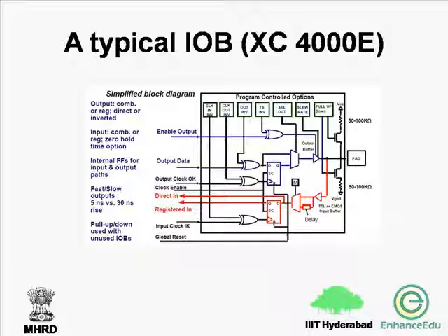So from a technology point of view, in an FPGA chip, the same pin can be used as an input or an output port, but because of the connectivity restrictions in the board, in which a pin is either connected to an input port or an output port, the specific pin in an FPGA chip is either used as an input pin or an output pin, not both at the same time.